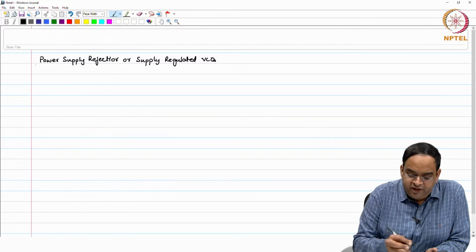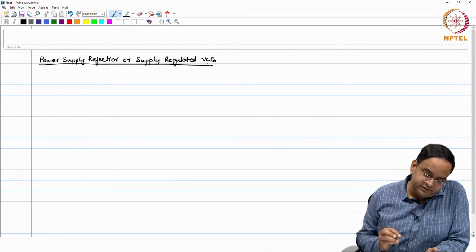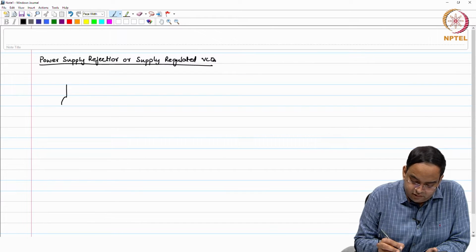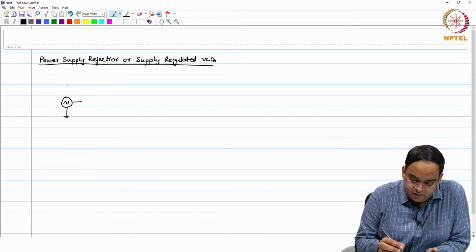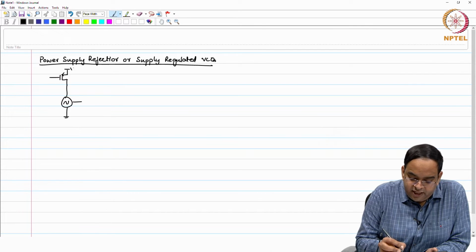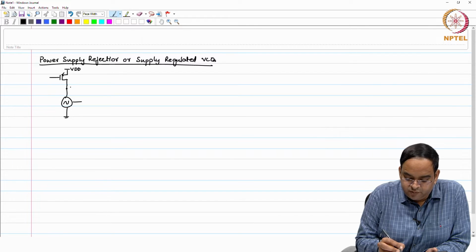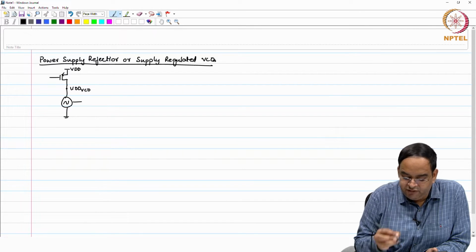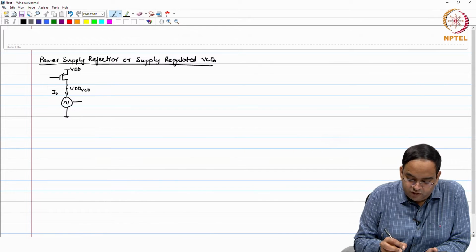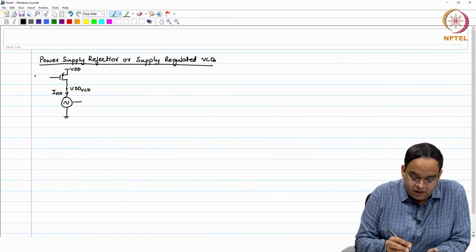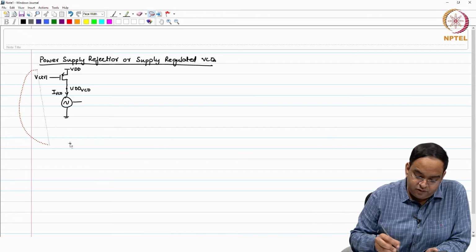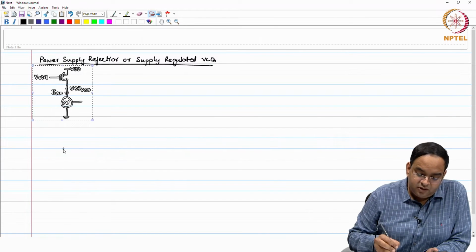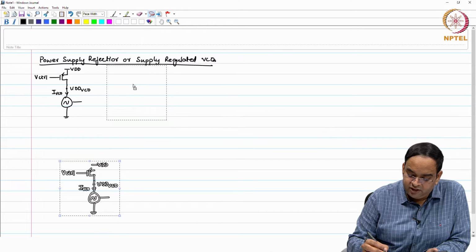So, what we have seen so far is that we have an oscillator, and the oscillator is controlled either by PMOS or by NMOS. This voltage I call VDD VCO, and the average current flowing through the oscillator is I VCO. You have a control voltage here, and similarly you have NMOS control where everything remains the same, only in place of PMOS you control with NMOS.